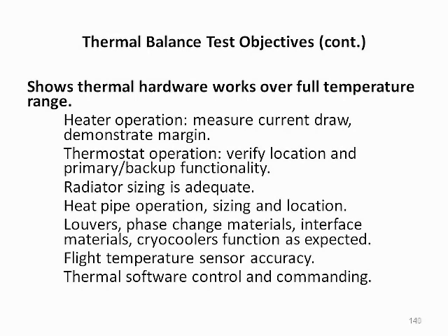Performance of the thermal control subsystem hardware is also demonstrated during thermal balance tests. For heaters, current draw is measured and control authority margin is demonstrated. The location and functionality of thermostats is verified. Radiator and heat pipe sizing and operation is confirmed. Louvers, phase change materials, interface materials, and cryocoolers are shown to be functioning as expected. Flight temperature sensor accuracy is assessed, and thermal control software and commanding are exercised.